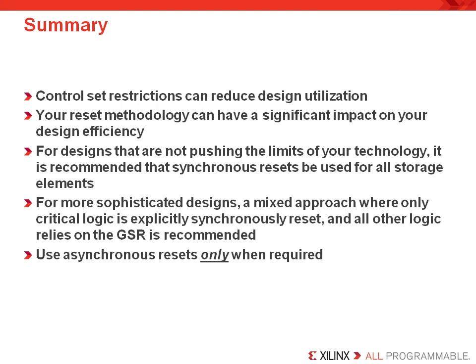For designs that are not pushing the limits of your device utilization or performance, it is recommended that synchronous resets be used for all storage elements. That's for memories as well as flip-flops and DSP slices. For more sophisticated designs, a mixed approach where only critical logic is explicitly synchronous reset and all other logic relies on the GSR is recommended.